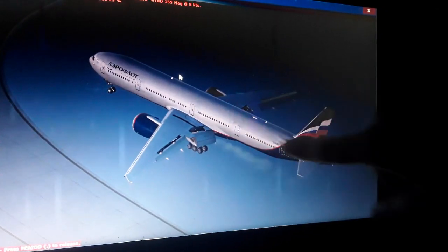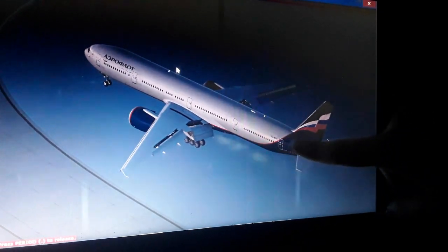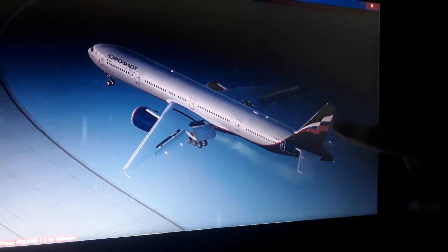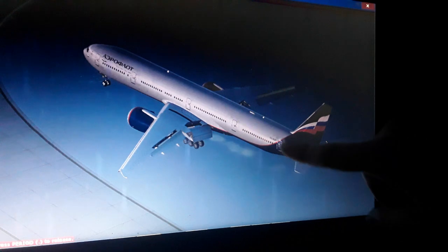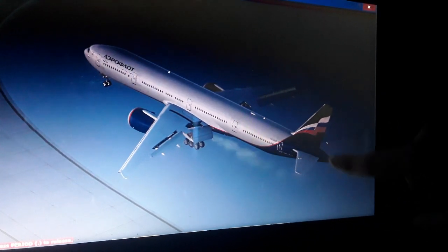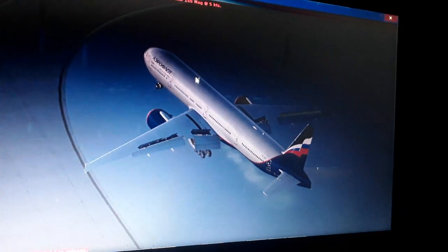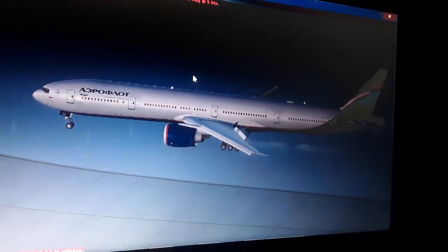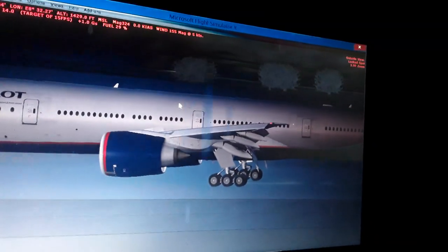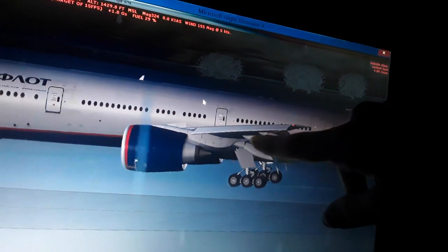So it's times the distance from the center of gravity all the way back to the horizontal or vertical tail, times the airflow of the air mass per second, times the acceleration of the Earth's gravity. Also you can see the same applies for the ailerons and the spoilers in the left and right wing. Also we have the lift using the Bernoulli theory, fluids, and Newton's physics.